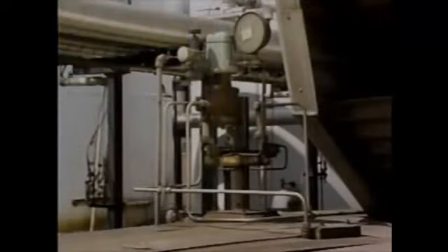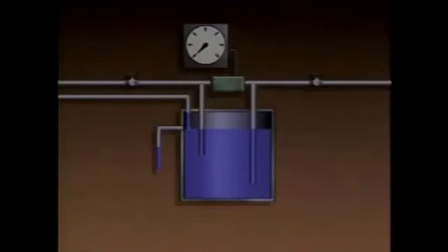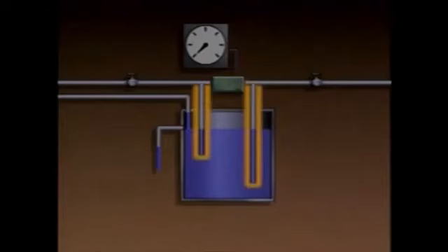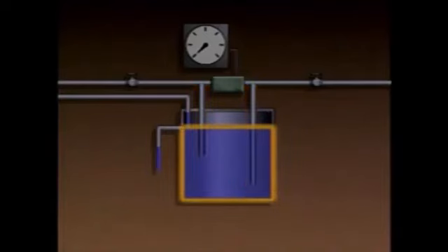But some systems, like this density bubbler system, allow for continuous density measurements. The operation of this density bubbler system is based on the fact that the difference in pressure across a differential pressure, or DP cell, depends not only on the difference in the length of two bubbler tubes, but also on the density of the liquid in the tank.